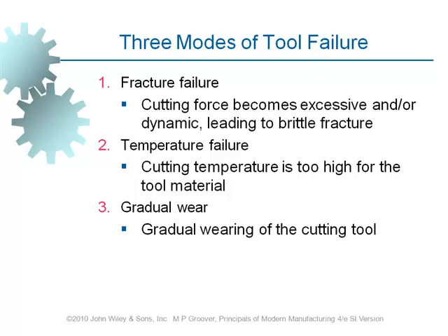However, please note that in doing so, we are also lowering productivity. So we've got to compromise between productivity and tooling cost. Okay? If we lower the cutting speed and also feed rate, you can increase the tool life of the component. However, would that be profitable if you make just a few parts per day to make your cutting tool last a really long time? It won't be economical.